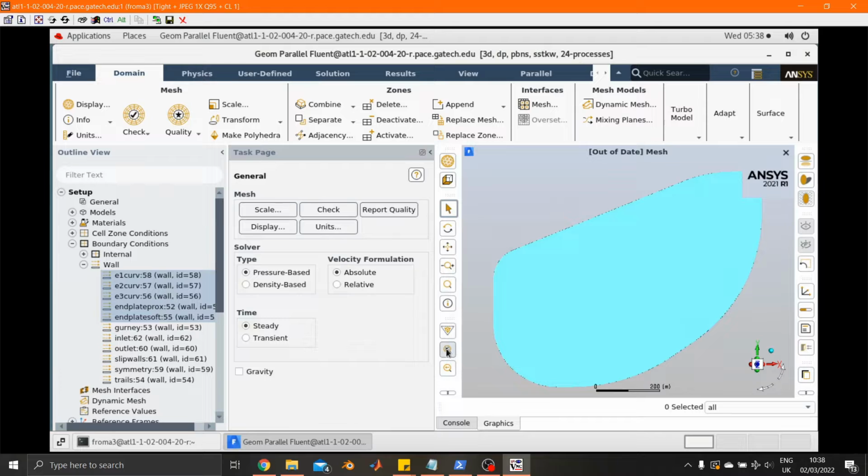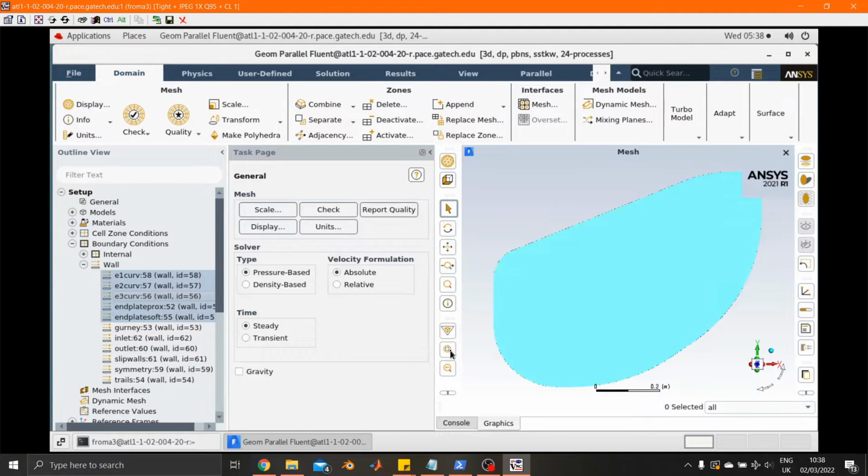refresh this view. So if we right click on these again and go to display, we'll see that it suddenly goes very, very small. We'll zoom into it again, and you'll see the wing is now about 1 meter long, which is what we want. So that's the first step you should always do. Just make sure that the length is correct, because you'll get very dodgy results otherwise. Okay, so once we've done that, we can then move into all of the setup.